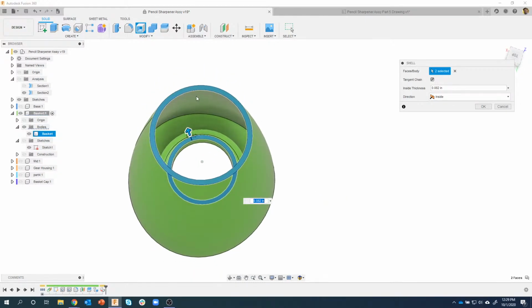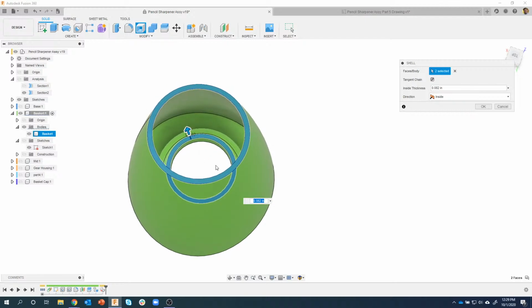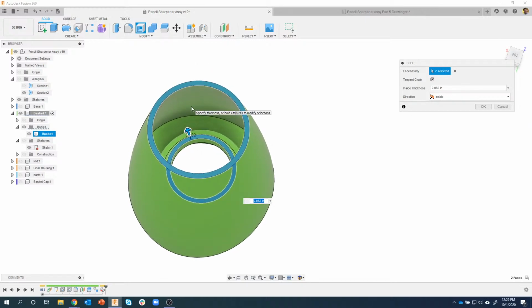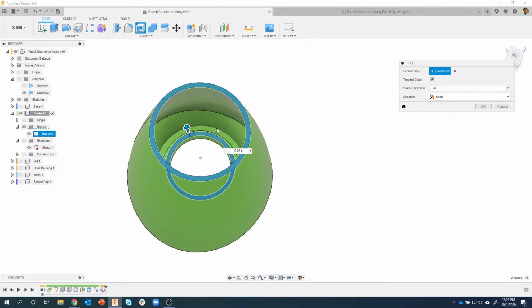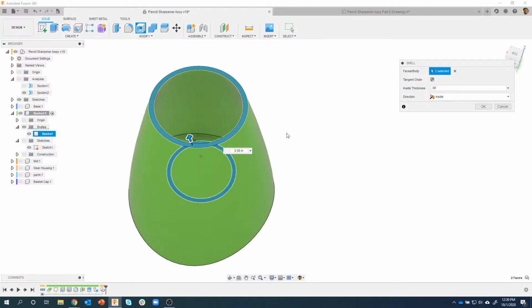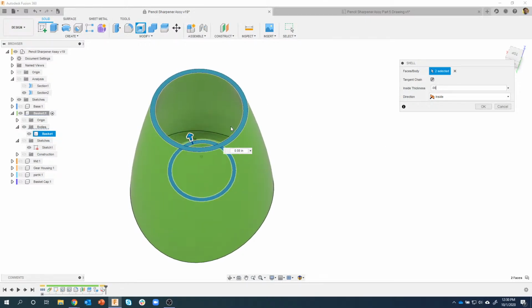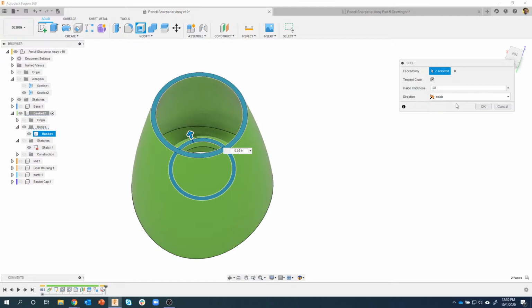We can see down inside of it, and we can see all the way through it because we opened it up in the top and we opened it up on the bottom. And I was actually pretty close, 0.08 for the wall thickness, and we're going to make it go to the inside. We don't want the overall outside to get thicker. We want the inside direction.